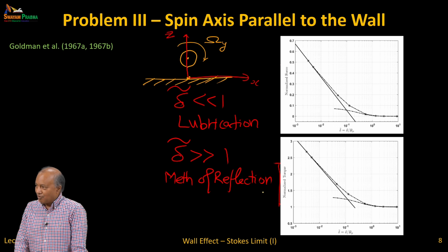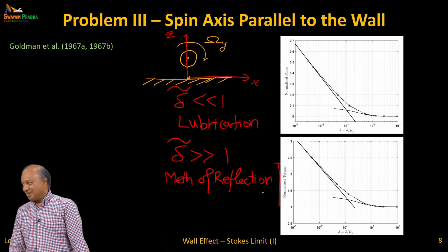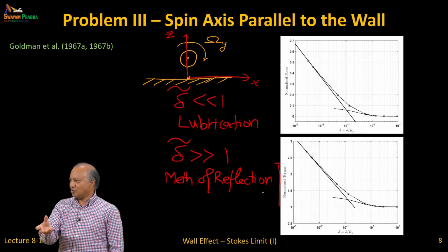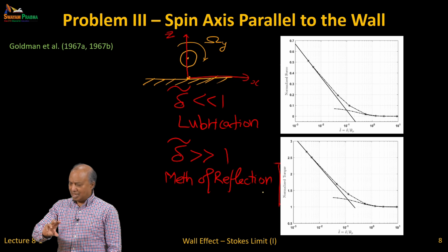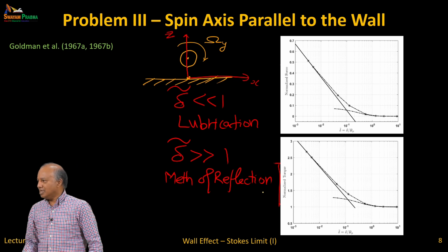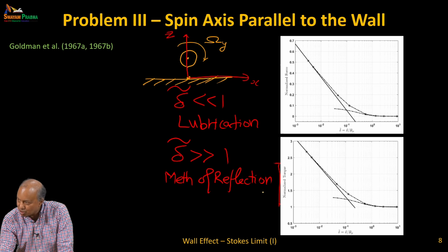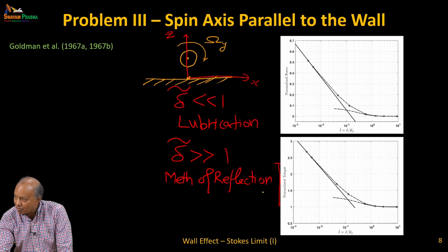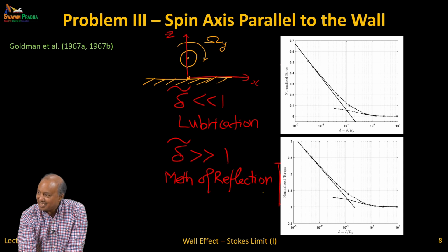If you put a shear flow, the particle will experience a force, but it may not move, because it will actually also rotate and move. It can rotate. If it rotates, then there are similar results. For a rotating particle on a plate, a rolling particle, that's the right word, there are results. I am not talking about giving the rotation to the particle. I am talking about the rotation which will be created by the fluid. Yeah, that's what I'm saying: when you have a particle close to your wall and you apply a shear flow, it can't slide.